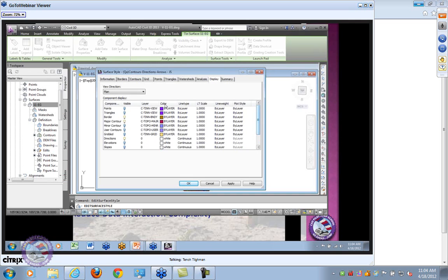any. And notice in plan here, we're getting major contours only. Okay, no minor contours at all. We're getting a skirt border, no points, right? And then only one slope arrows, right, are being shown, and directions are being shown. Both directions and slope arrows are all going to layer 0 by default. They're white. How come they're colored?